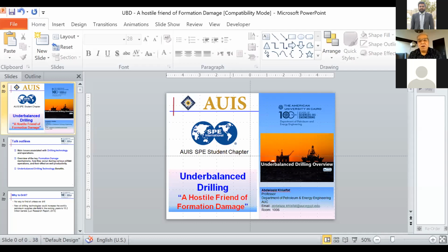With overbalance, there might be no issue, because when we hit the reservoir, we don't produce right away, or we shut in the well. But with underbalance, because of the simultaneous production while we drill, we have to be ready for this. So this is another issue that we have to take care of when it comes to offshore.